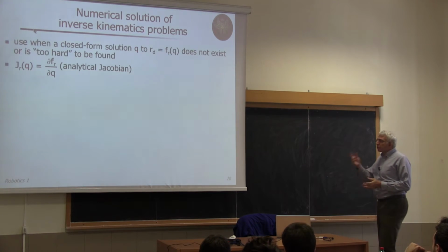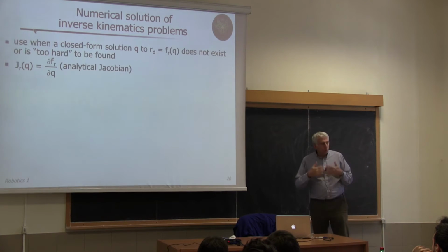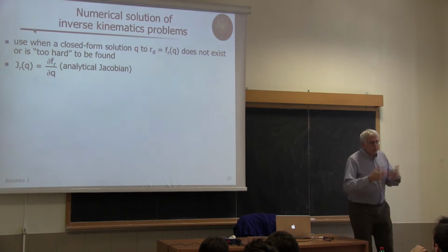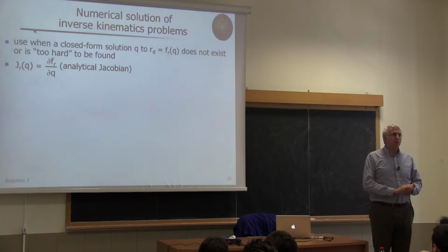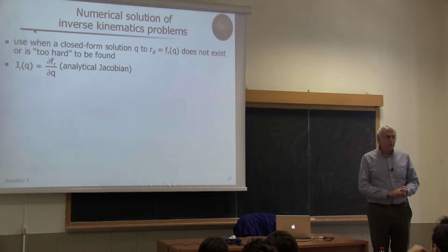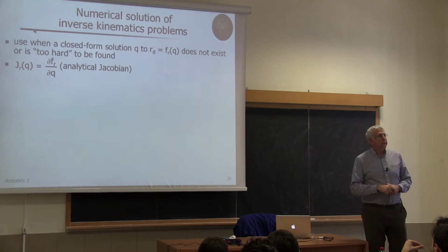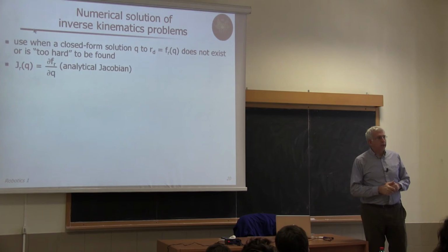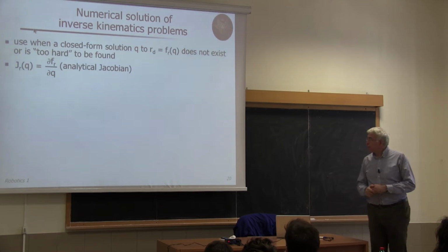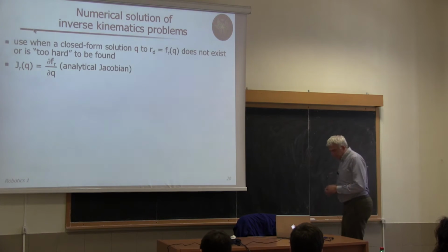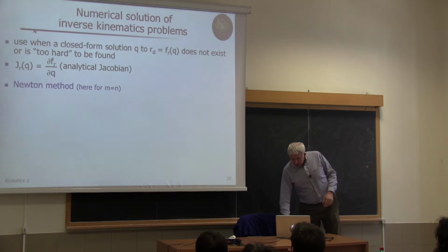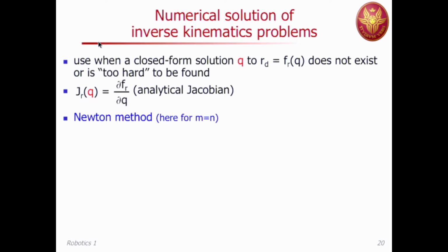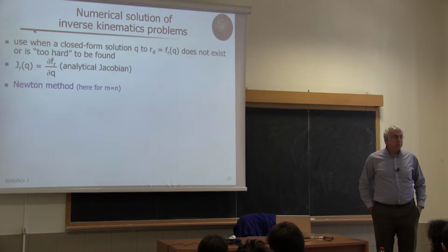So what we need to do is to compute the forward direct kinematics or task kinematics, f_r(q), and build this matrix with partial derivatives in the way that we have illustrated on the blackboard, I think last lecture. With this matrix, which is in general an m by n matrix, we can introduce the different numerical approaches.